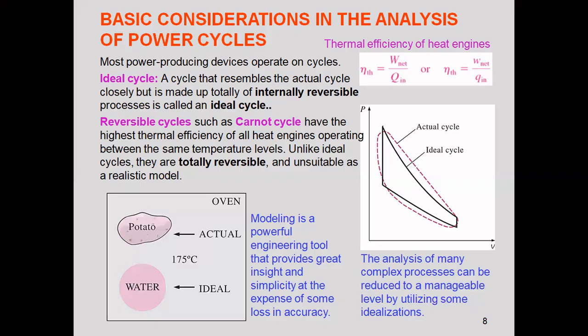Therefore it is maximum. Once the losses are included and the deviations are taken into consideration, there will be some reduction in the efficiency, work done, etc. Because in some processes we consider isentropic, meaning reversible adiabatic, right? So in the actual situation it will be neither reversible nor adiabatic. Reversible means it should give you the maximum efficiency, and adiabatic means there is no heat loss, so neither heat loss nor heat transfer from the surroundings to the system.